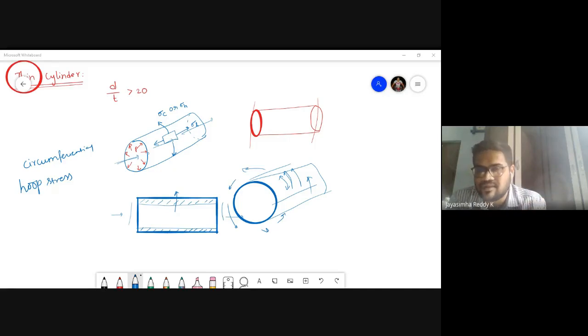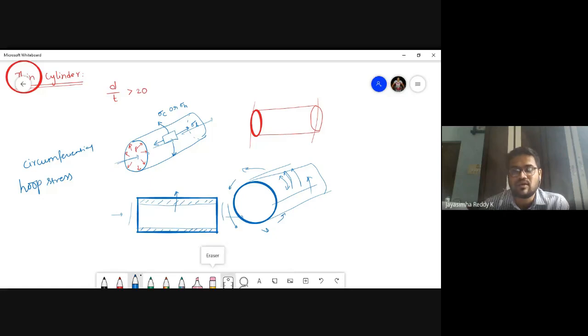So stress is nothing but the opposite force induced by the material to withstand that pressure. అంటే మనం అప్లై చేసే ఫోర్స్‌ని విత్‌స్టాండ్ చేయడానికి మెటీరియల్ ఒక రెసిస్టెన్స్ ఆఫర్ చేస్తుంది. ఆ రెసిస్టెన్స్‌నే స్ట్రెస్ అంటున్నాను. అలాగే ఇప్పుడు పైప్ కానీ సిలిండర్ కానీ మీరు ఏదైనా అజ్యూమ్ చేసుకుంటే, ఇన్‌సైడ్ ఇఫ్ దెర్ ఈస్ ఏ ప్రెషరైజ్డ్ ఫ్లూయిడ్, then the material on the circumference will offer certain resistance to the pressure applied. So that resistance is called circumferential stress or hoop stress.